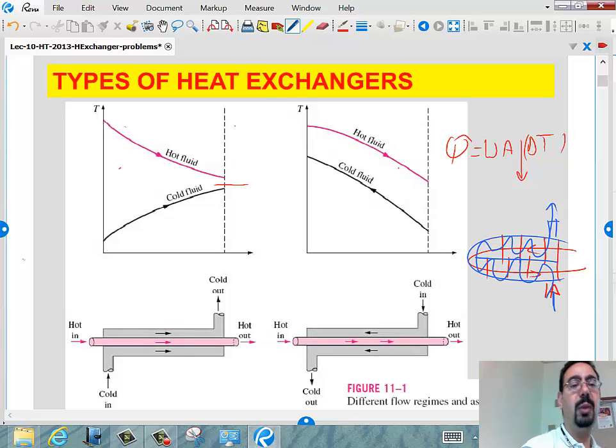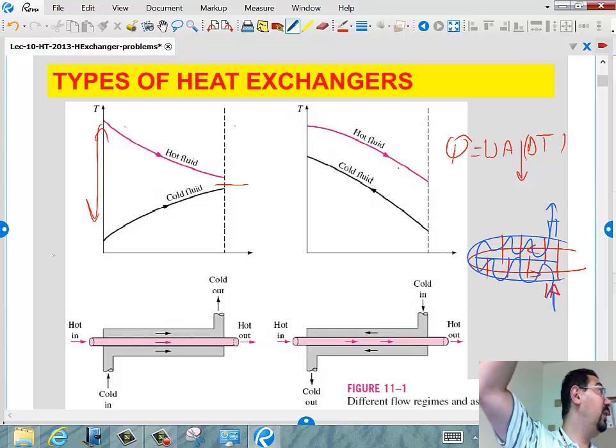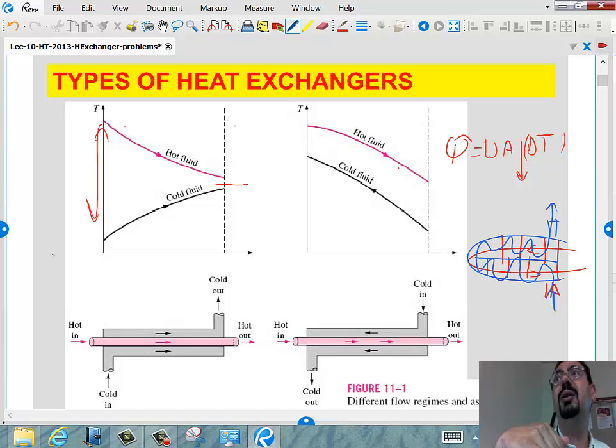Right, but I'm a thermofluids person, I don't care about the material. From a thermo point of view, not a material science point of view, this is a waste of availability. This will increase the entropy of the system. This reduces the efficiency of the cycle. Anytime you use very hot fluid to heat very cold fluid and you have a huge delta T between them, that makes your cycle efficiency really drop.